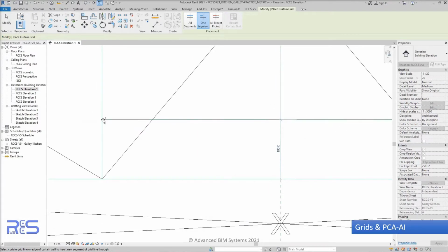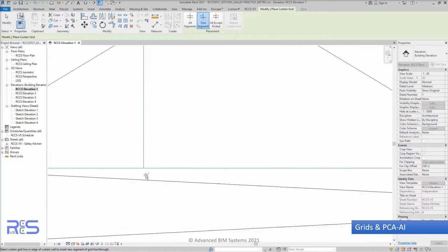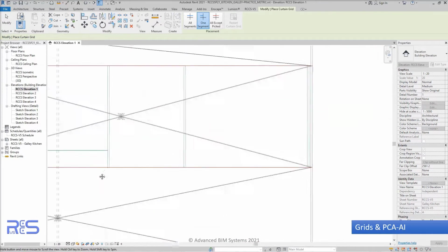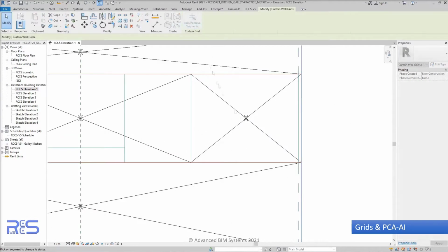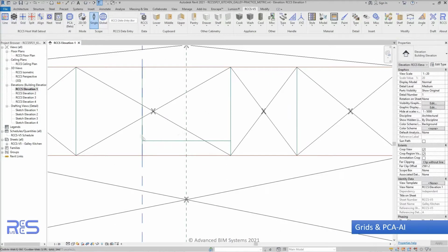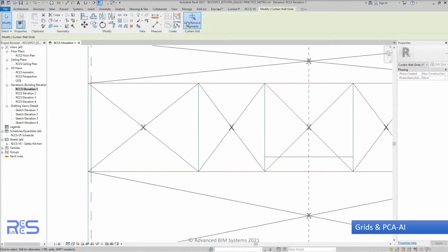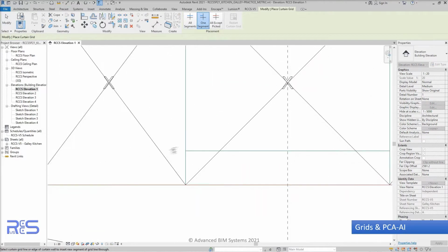This simple sketch could also be created inside of Revit using detail lines. We found that quite often these simple sketches allow designers to be able to gather their ideas and determine locations for where they wish to place components. Right now we're subdividing the grid using the AutoCAD drawing in the background so that the software will then be able to place components into these grid cells.